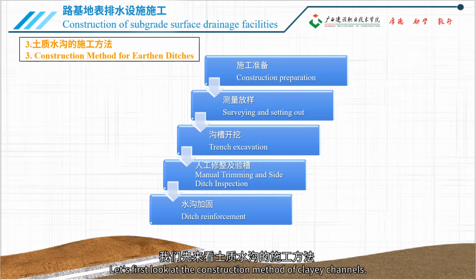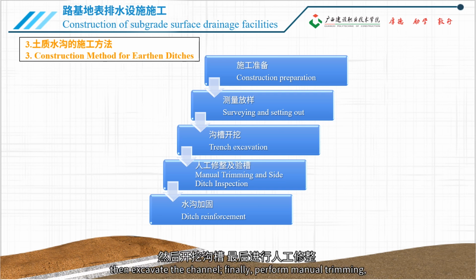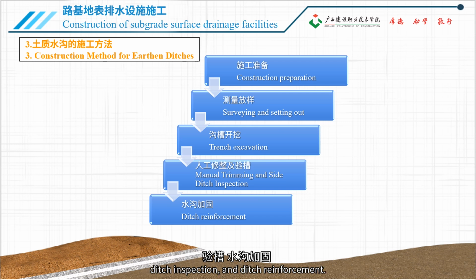Let's first look at the construction method of clay channels. First, carry out construction preparation, survey and setting out. Then excavate the channel. Finally, perform manual trimming, ditch inspection, and ditch reinforcement.